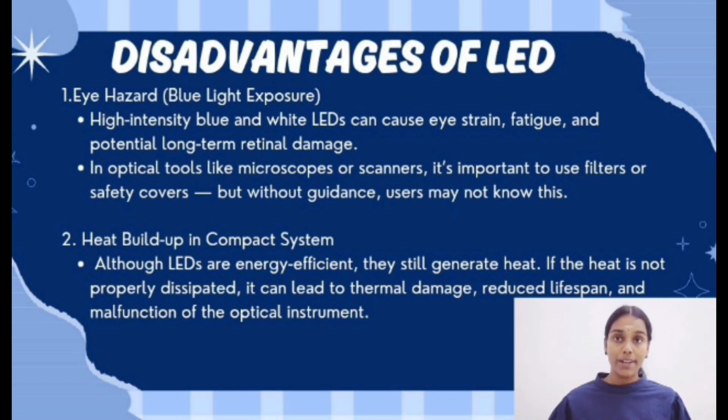So in compact instruments like small optical sensors, heat cannot escape easily. If not managed properly, it can lead to thermal damage, reduce the LED lifespan, or even cause the instrument to fail. That's why proper cooling mechanisms are very important in this system.